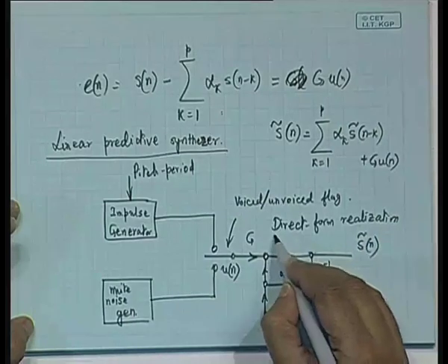Now, direct form definitely has an advantage, because the direct form realization is a very simple realization. It is easy to implement, but on the disadvantage side, it has sensitivity with respect to the variations in alpha 1, alpha 2. So, variations in these alpha values make the realizations sensitive, and there are alternative forms of filter realization which are possible.